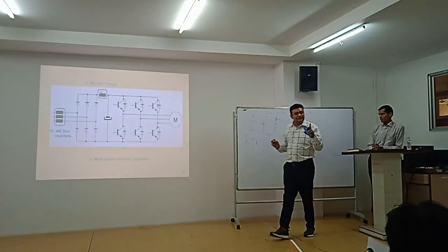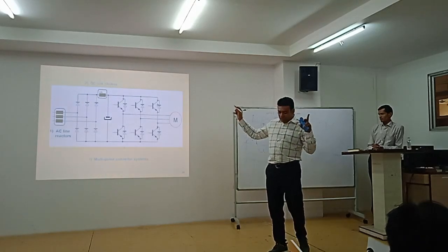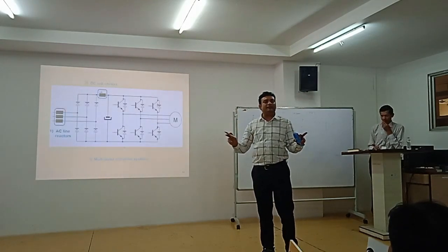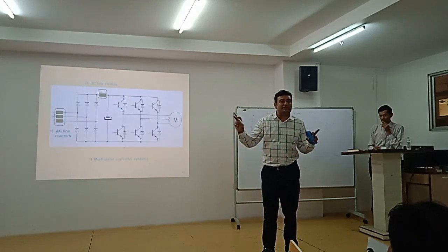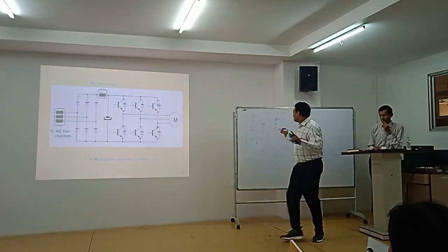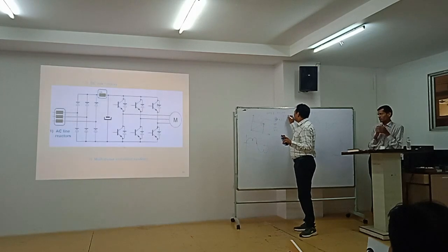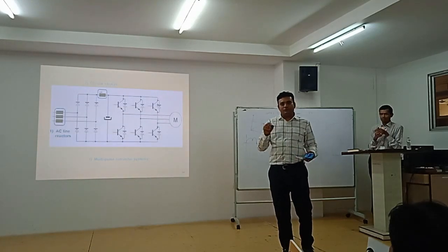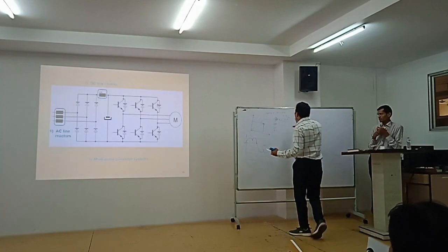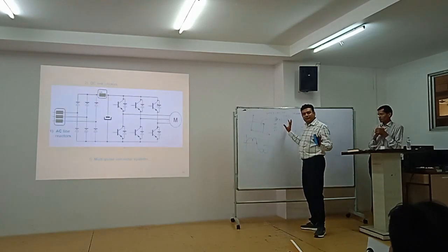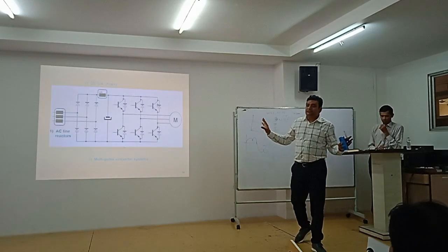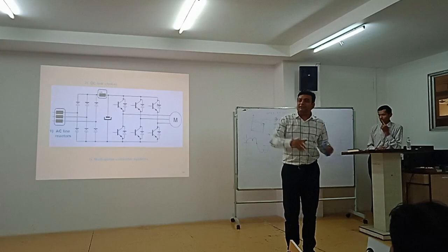Then take k equal to 1 and P equal to 6. If you go for a 6 pulse rectifier, a 3 phase rectifier, the output will be 6 pulses on DC. So here it is 6 plus or minus 1, so 5 and 7, and naturally the third harmonic will be out. So the formula is more or less kP plus or minus 1, and that decides which harmonics appear in the system.